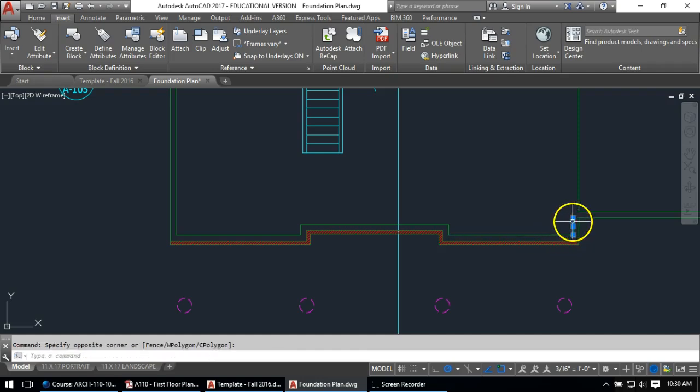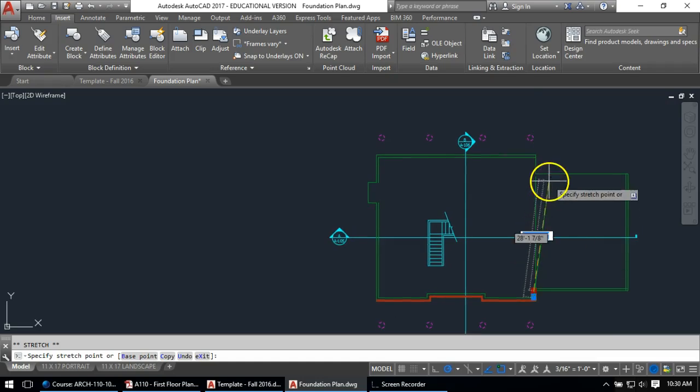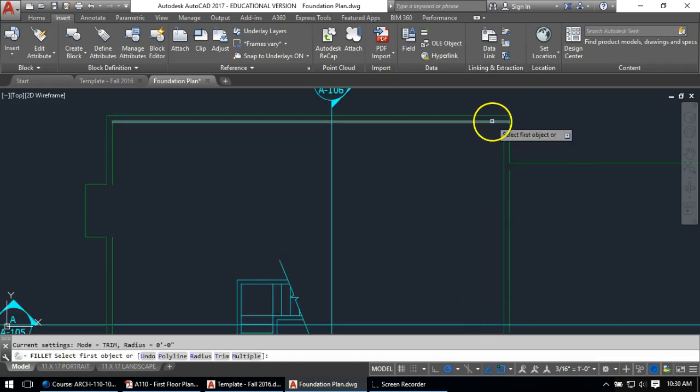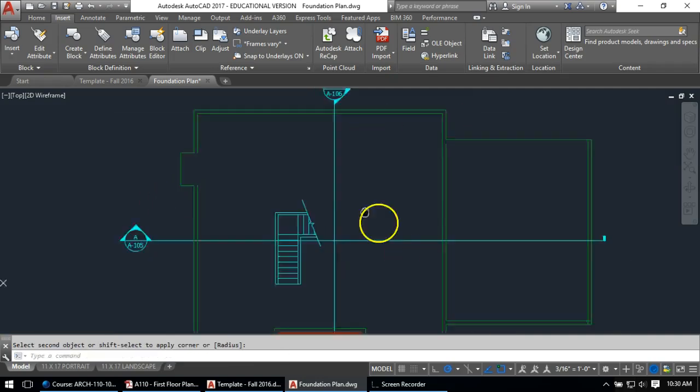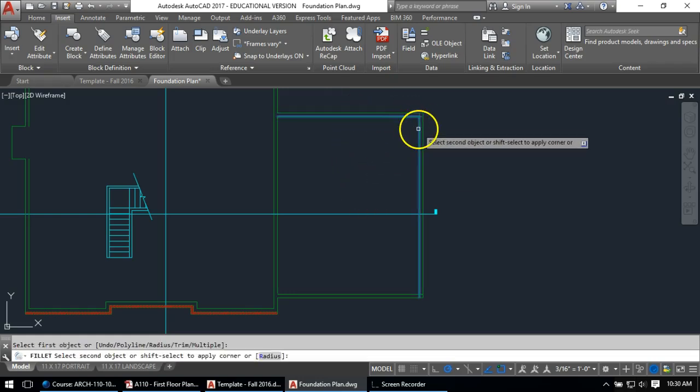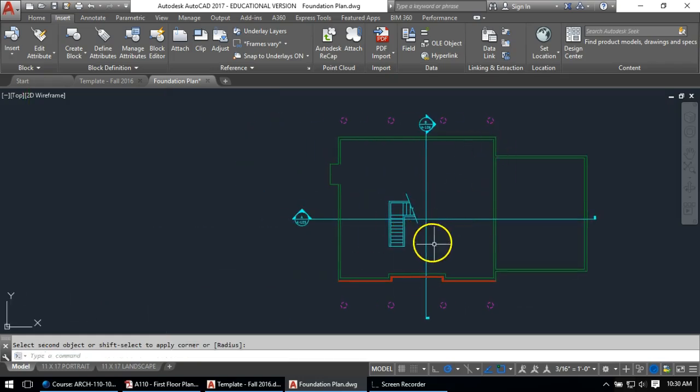This one, I always like to keep straight lines. So yes, this will be broken up at some point, but rather than offsetting 3 lines here, I'm going to make them all one line there, and offset that guy. Fillet it here and fillet it here. So there we go. There's my exterior walls. A good enough start for now.